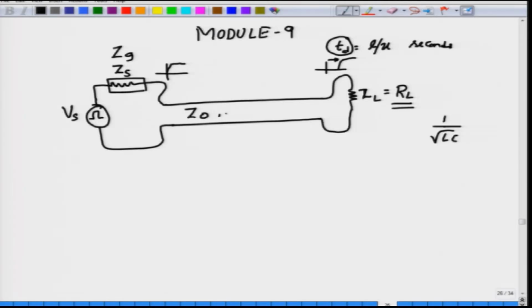So, normally we give you Z0 and Td, we rarely give you the length and the velocity, but if they are given, then it is easy for you to find out Td from this relationship, and it is important to note what Td is. Okay. And all these things come simply from assuming the time domain behavior of the voltages is given in the form of V of t minus Z by U, where V is basically the voltage that is propagating.